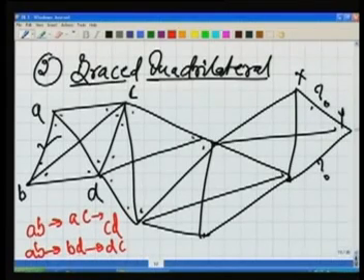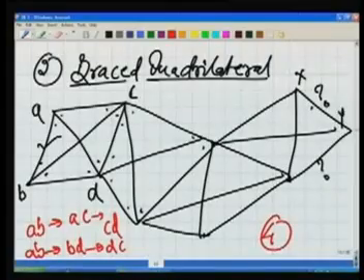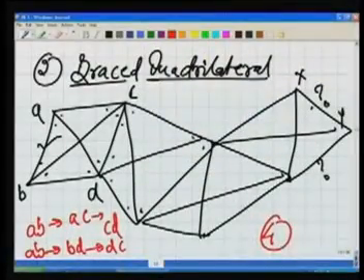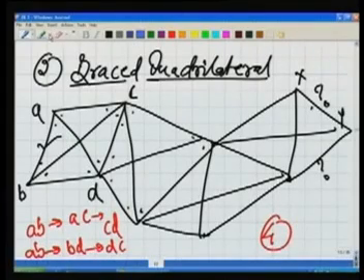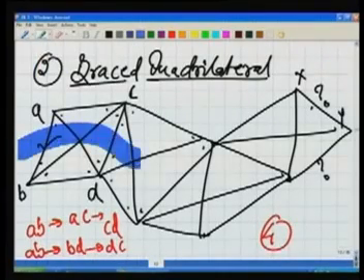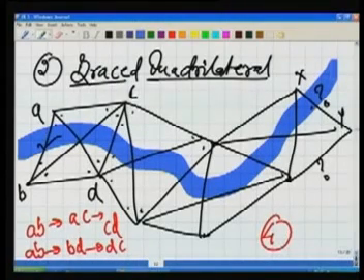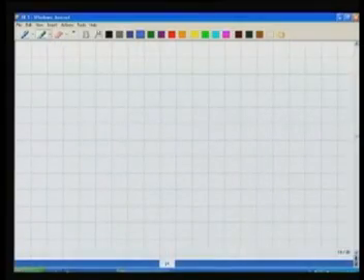In this figure, as you will see, there are 4 possible routes. So we have a check on our computations, and we will see later on that we can choose a route which is the best for the computation. So this figure has this flexibility. This figure is said to be the best figure. Now where can we make use of this figure? We can make use of this figure in order to create, as in the case of our river also, for example, a simple river, a chain of the braced quadrilaterals, or maybe in some other case, let's say a hilly terrain. I am drawing the contours just to show the hills.